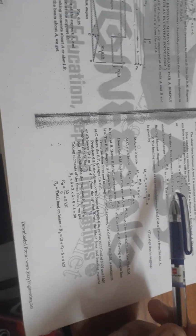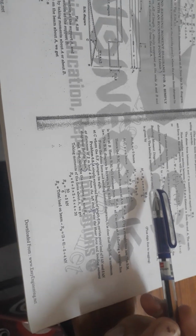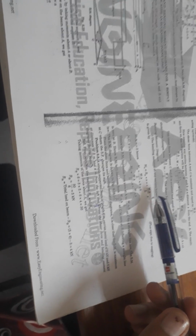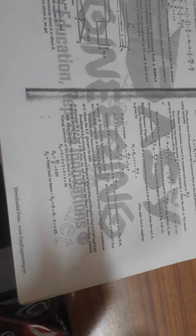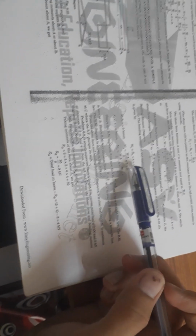Bending moment at any section between A and C at a distance x from the free end A is given by Mx is equal to Ra into x, which is equal to plus W into B by L into x. At A, x is equal to 0, then MA is equal to W into B by L into 0, which is equal to 0.